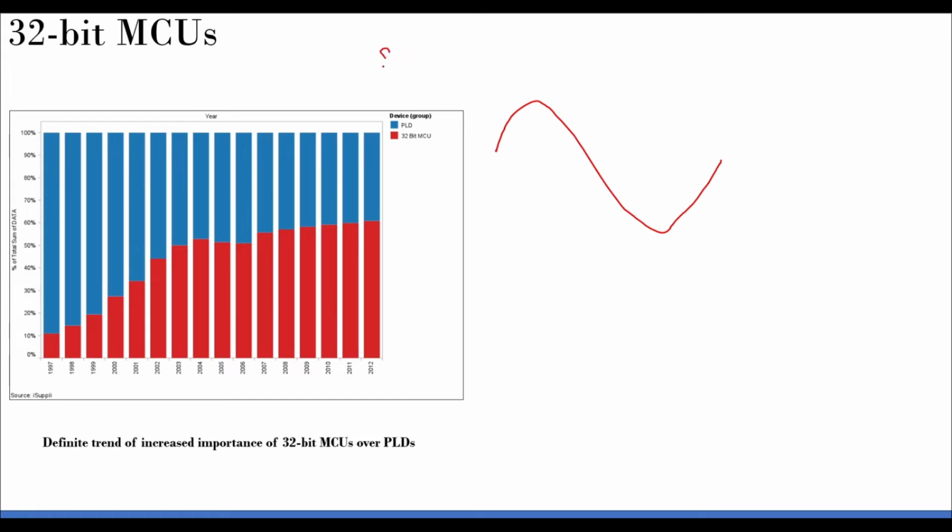So let's say 8-bit. 8-bit literally means you have 2 raised to 8, because with 8 bits, 2 raised to 8 combinations are possible. This is something like 128, in fact 256, right? Yes, 256 is what you get. So literally this means this waveform is getting divided into 256 levels.